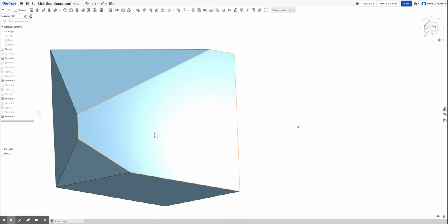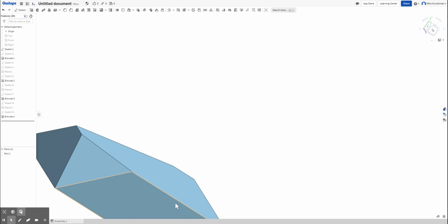Okay, so all we did was create a new sketch on the surface, put in 2 points using the point tool. We finished that sketch, went to the plane tool. From the plane tool, we pulled down to a 3-point plane, click, click, click, make a new sketch on that plane, make some kind of shape, boom, extrude.